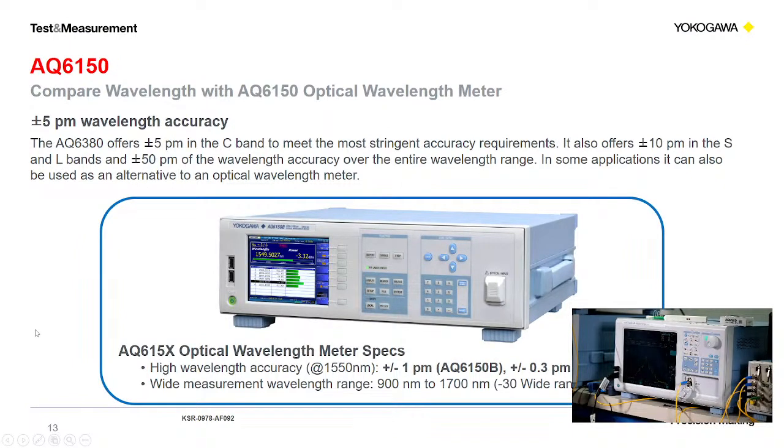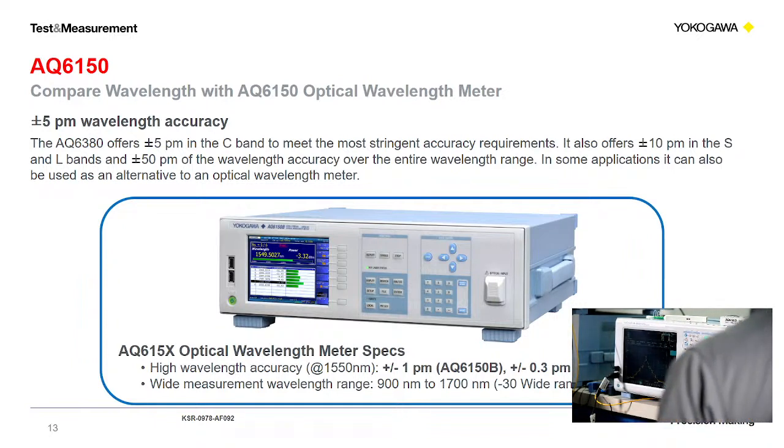So next thing we want to do is, we talked about the resolution, 5 picometer, but the wavelength accuracy is also now at 5 picometer, so that's also considerably better than our traditional OSAs. In fact, it's actually much closer to our optical wavelength meter specs, which is 1 picometer for the standard model and sub-picometer for the higher accuracy model.